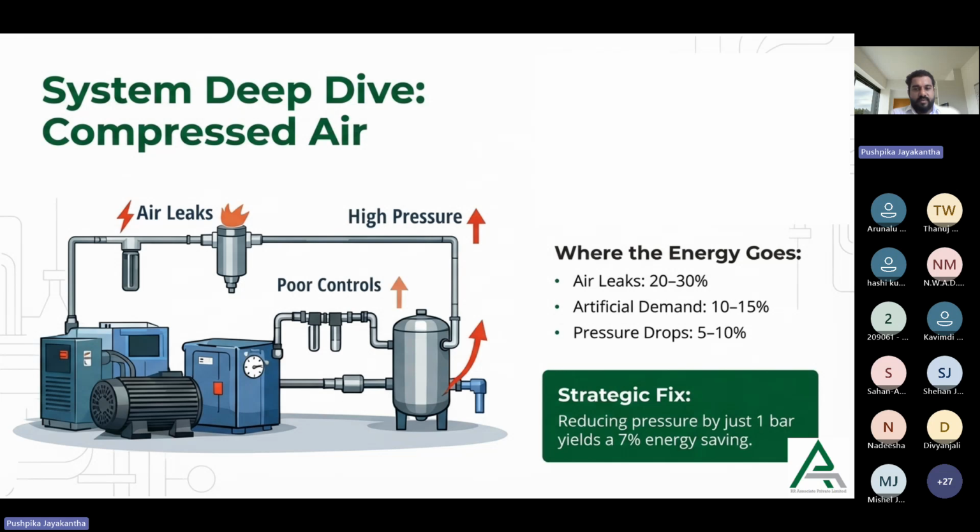So what happens when filters are blocked? The airflow resistance increases, the compressor must work harder to draw air, and a pressure drop occurs across the filter. This increases the load on the compressor motor. That's why preventive maintenance is very important.